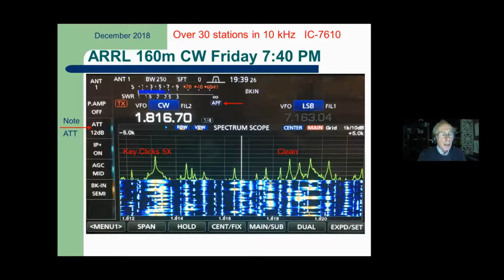The other thing is there's no reason to have the AGC running on band noise. And we don't see too much of that on 10 meters, we hope. But on 160 it would be typical, and the S-meter would be running way upscale. So I like to set either with the attenuator or RF gain, or with, for instance, the Flex or the Apache, they actually have a separate adjustment for AGC threshold. I want it to be above band noise.